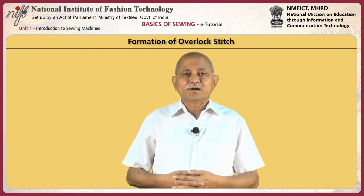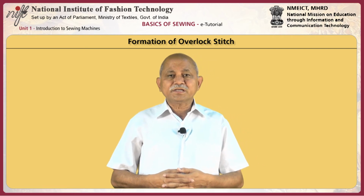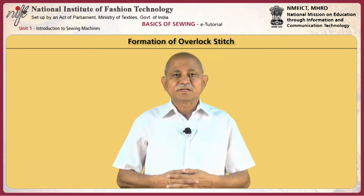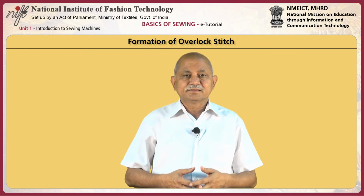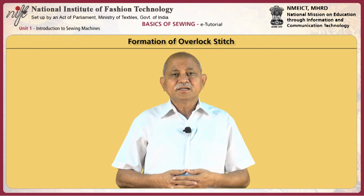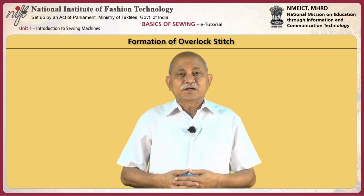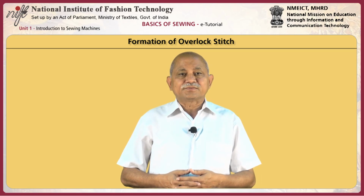The tip of the upper looper passes behind the lower looper and picks up the lower looper threads and needle thread. The lower looper now begins its move back into the far left position as the upper looper continues to the left.